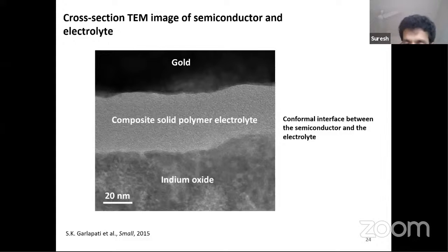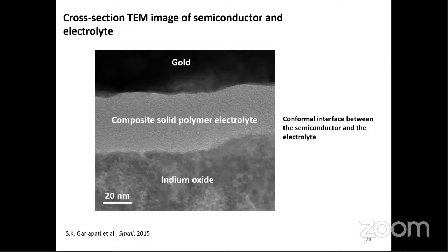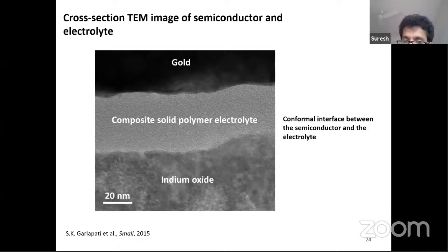Yes. So how it works is, again, you can have, in this case mostly, a field emission gun. Here you can generate the electrons from the field emission gun. These electrons have to travel through the sample. The sample has to be very thin, less than 100 nanometers in thickness. So when the electrons travel through such a very thin material, they will again interact with the material and carry the information about the material's structure, again through the scattering concept.